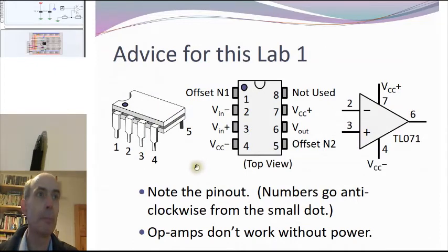A quick reminder about the single op-amp package that we'll be using in this lab. The pins are numbered anti-clockwise. Remember, everything goes anti-clockwise except clocks. They start at the corner here with the dot, and they number 1, 2, 3, 4, 5, 6, 7, 8 round in that order. And this is the industry standard pinout for a single op-amp in an 8-pin package.